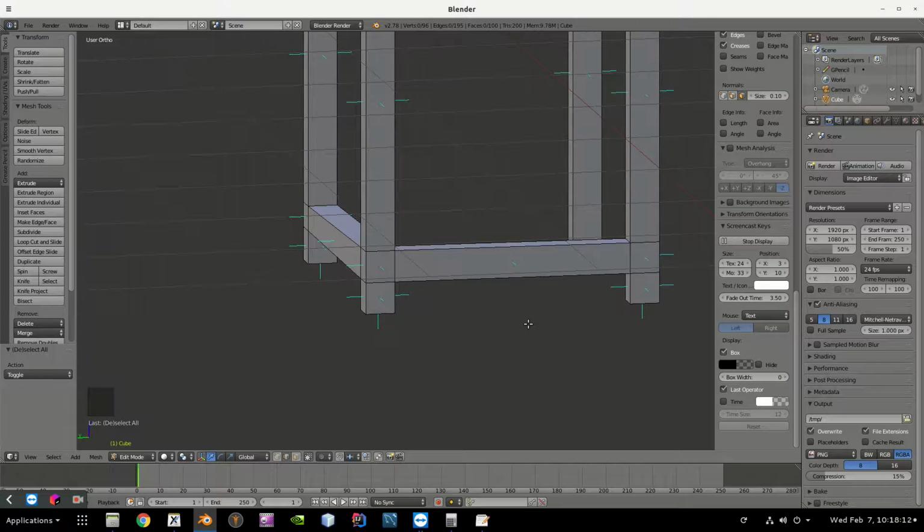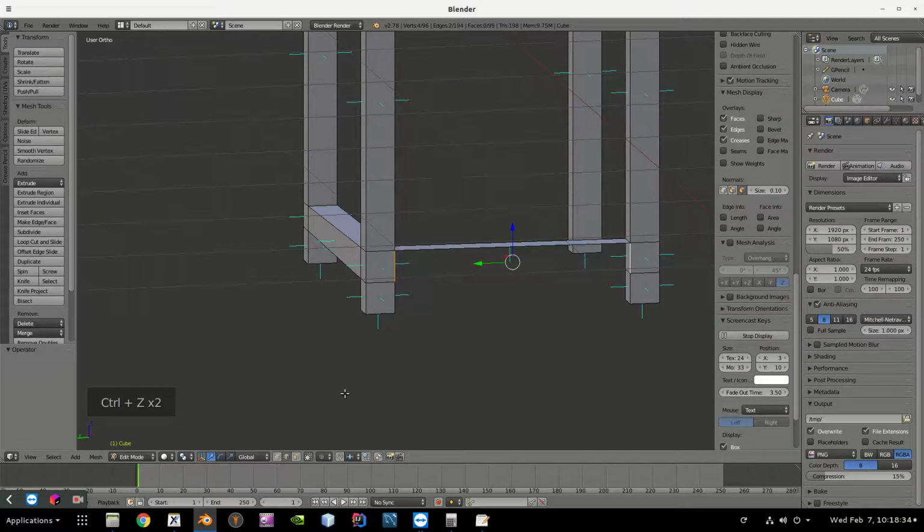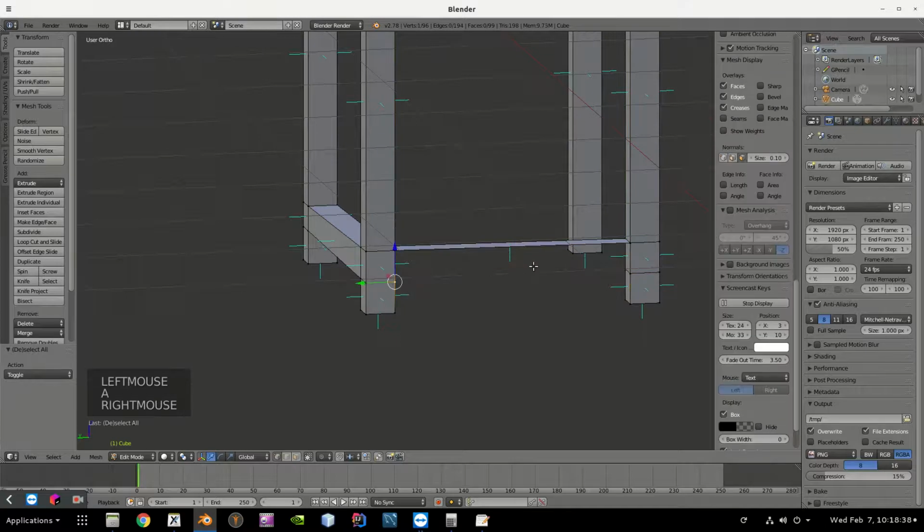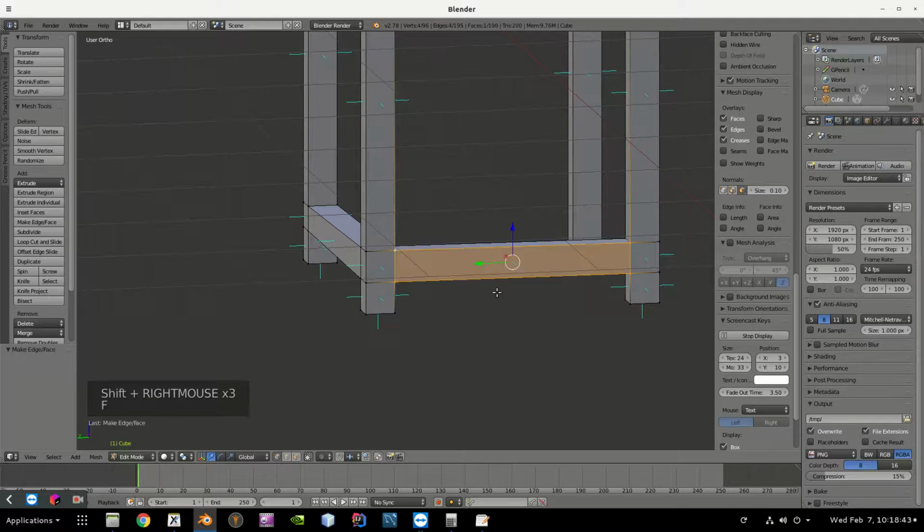The reason this surface normal will come out is because we have vector A and vector B. If you do a cross product like this, your thumb will show where it's going to go. But if you go the other way, that you take this one and then this one, then it's not going to work properly. Let me try to make it a little bit more obvious. And for that, I want to select the vertices manually. So this vertex, this vertex, this vertex, and this one form a face.